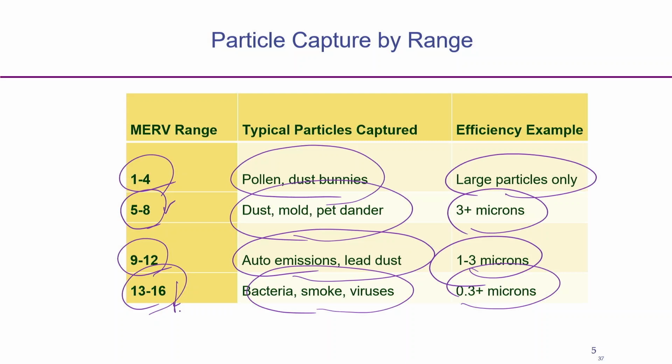You can see here that as we go from MERV 1 to 16, we are going towards finer particles, but the pressure drop also increases.